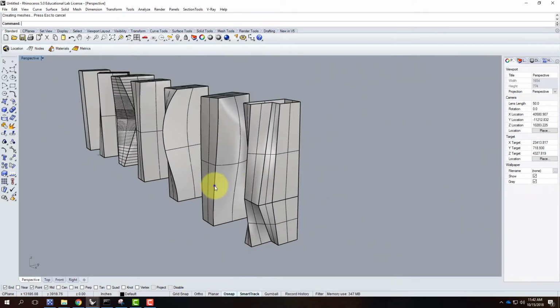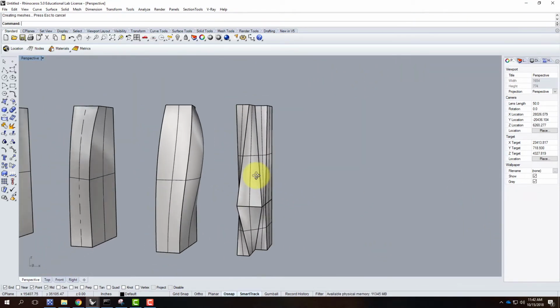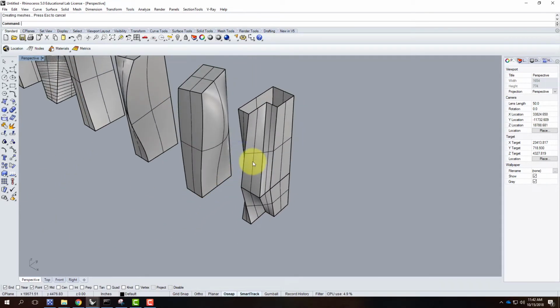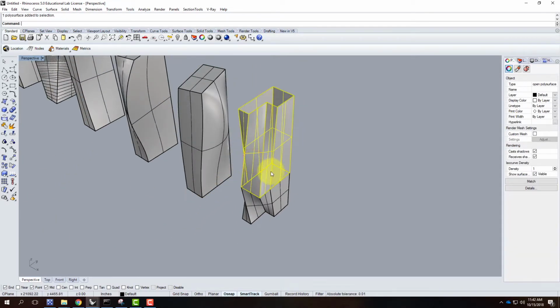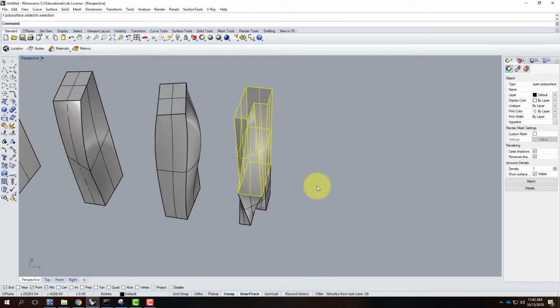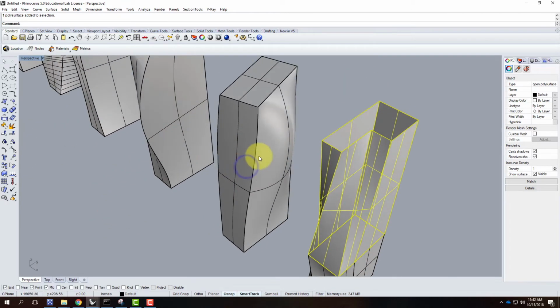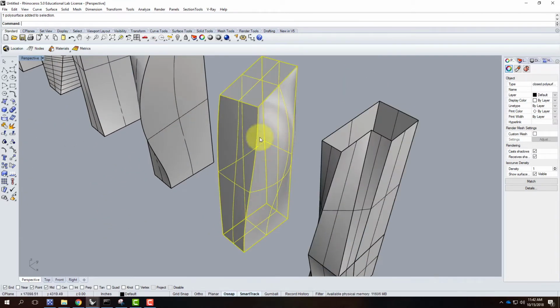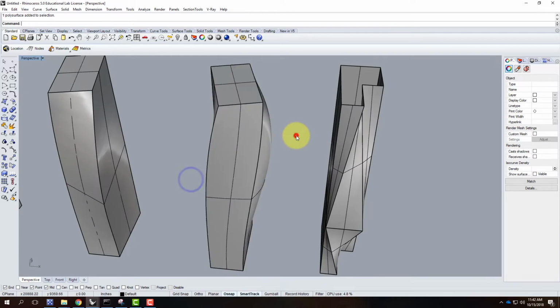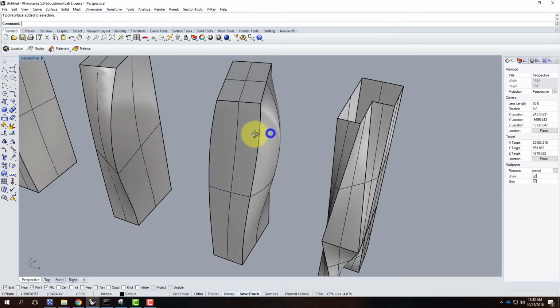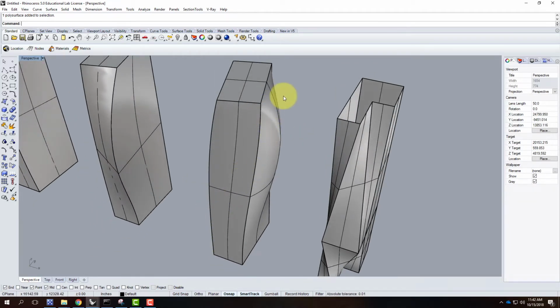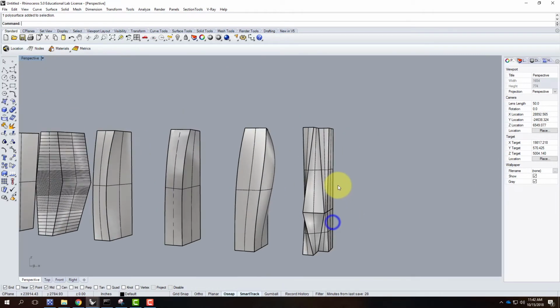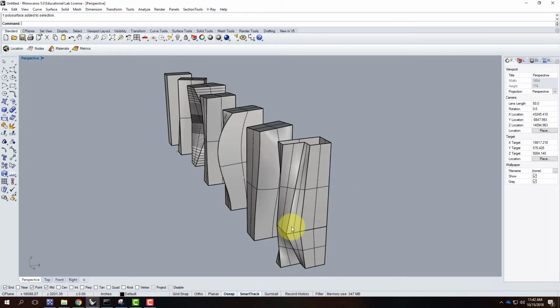So this is obviously a much different way of building up the skyscraper, but there's nothing wrong with building it this way. Same strategy. A loft by its nature is always going to be unrollable. So you're always safe. If you loft two things together, you'll be okay. In fact, when I ask people to simplify shapes later on, if you end up with this kind of a bulge by accident or maybe on purpose and you need to unroll it, what I'll have you do is duplicate the edges and then loft the edges together as a way of making it developable. So you can get creative and you can start to create something like this.